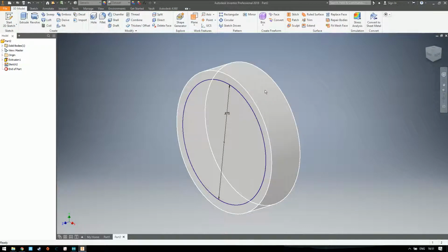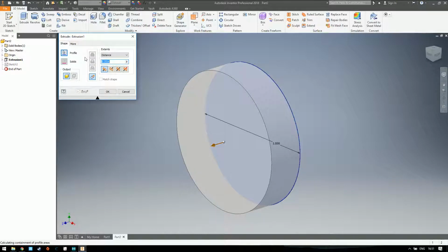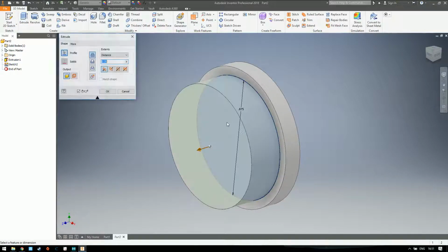Right now, you can see I clearly made the extrusion wrong over here. So you just left click on the cylinder. Then you can readjust the measurement of your extrusion. Then just extrude again. It will automatically depend on the sketch you just drew. This is the benefit of doing sketch layup, pretty much. So we just do that.